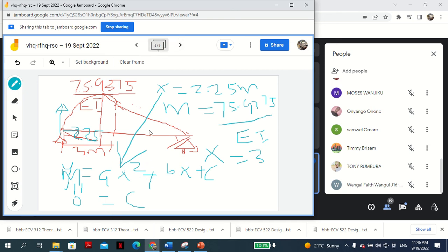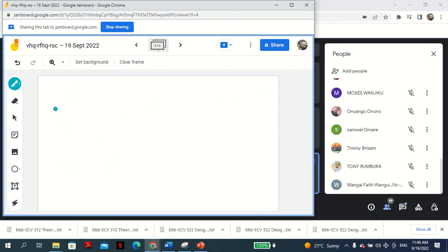Okay, let me just explain. The moment at 3 would be the point 67.5 times 3 minus 30 times 3 times 3 over 2. That would be the moment at point 3.